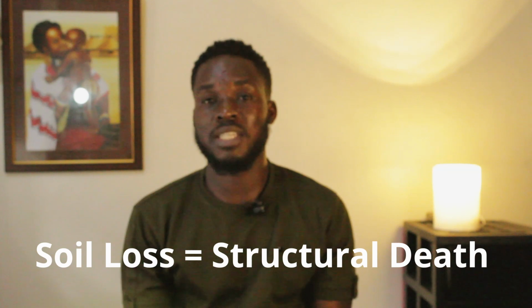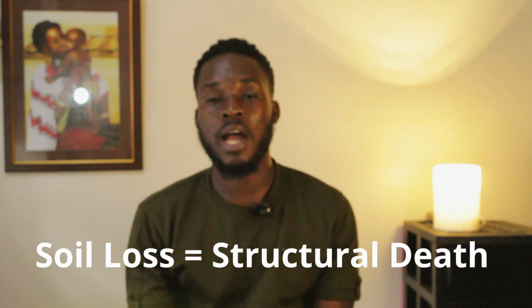The second one is seepage or piping. I call it the soil thief. Seepage doesn't just move water, it carries soil too, stealing the soil. When soil below the structure is swept away by groundwater, the structure becomes useless because it has no foundation where the weight will be anchored.